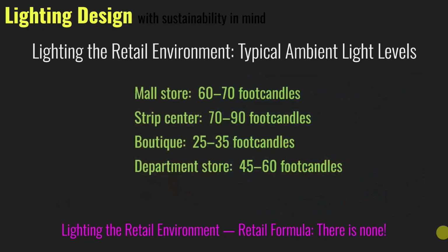All the different foot candle readings, the predicted amount is really important. You can see if your lighting layouts are uniform enough for your general lighting. Can you turn off the different layers of lighting? Okay, so you can see then, my general lighting levels, my ambient lighting, that's going to end up being 20 foot candles or 30, and is that enough? And then you go on and you see what other things add the spots that you do want to be brighter, with different levels of light, different types of lighting fixtures.